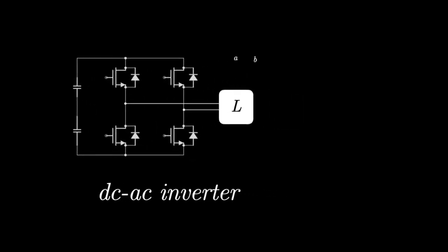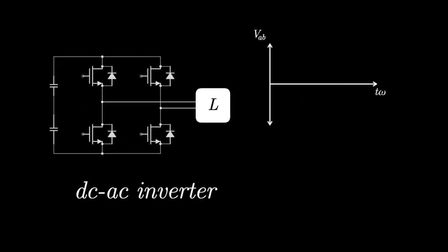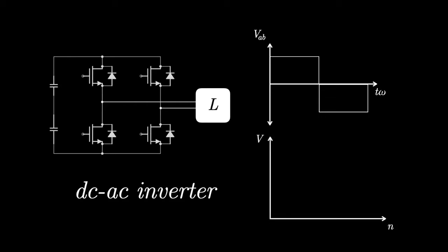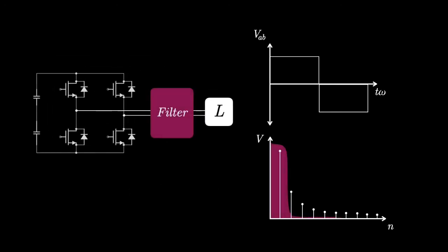The harmonics that are present in the inverter's output voltage are high for many practical applications because they can excite a mechanical resonance, causing the load to emit acoustic noise, and especially for applications where the output voltage needs to be near sinusoidal. Electric low-pass filters are normally added at the output to remove third and higher harmonics.